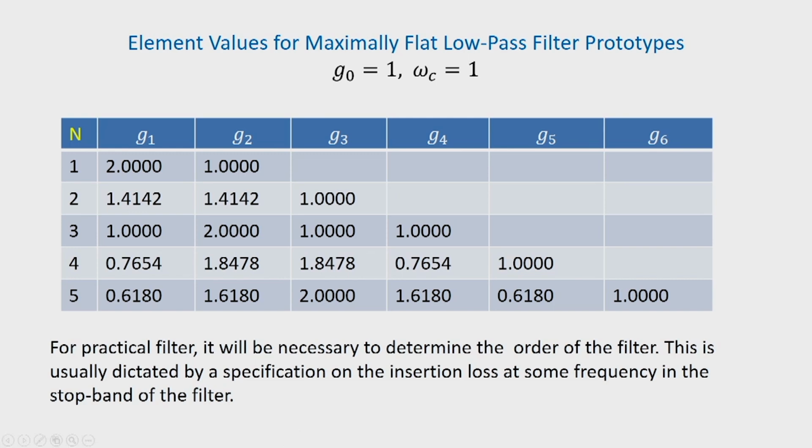And we can see that we found out in our second order filter L equal to C equal to root 2, which is 1.4142, and R equal to 1. So, G 3 is equal to 1. So, essentially we solved by our prototype circuit this row of the table.